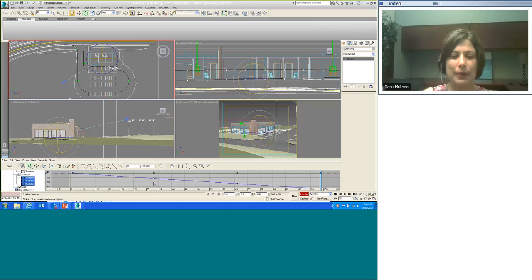So up here, you can choose the set tangent to slow. This button is set tangents to slow. So I'll apply that. And as you can see in the curve editor, instead of the linear interpolation, it is now slightly curved. So it will just move the animation turntable till here, and then it will slow down slightly